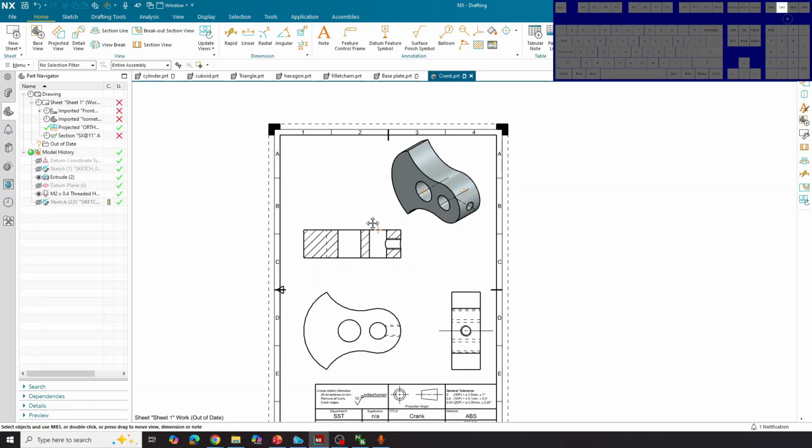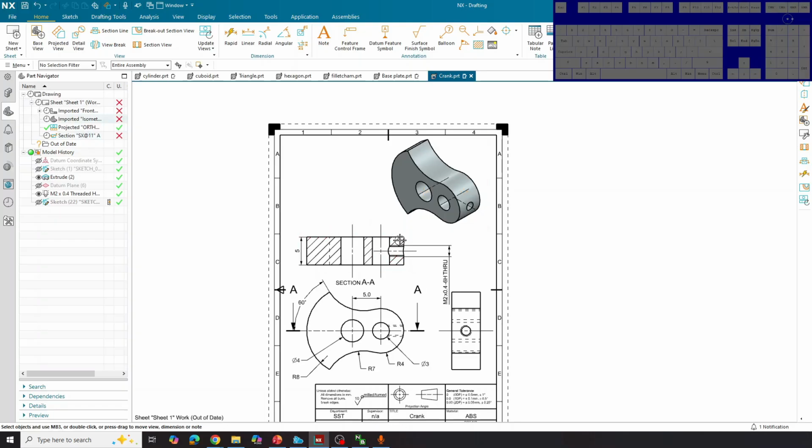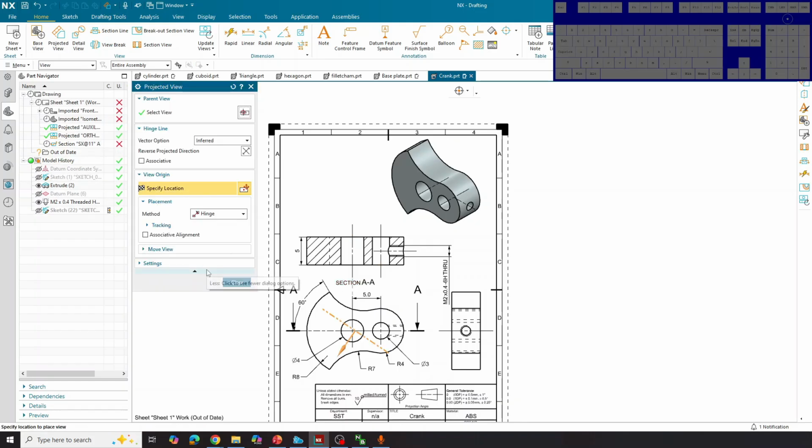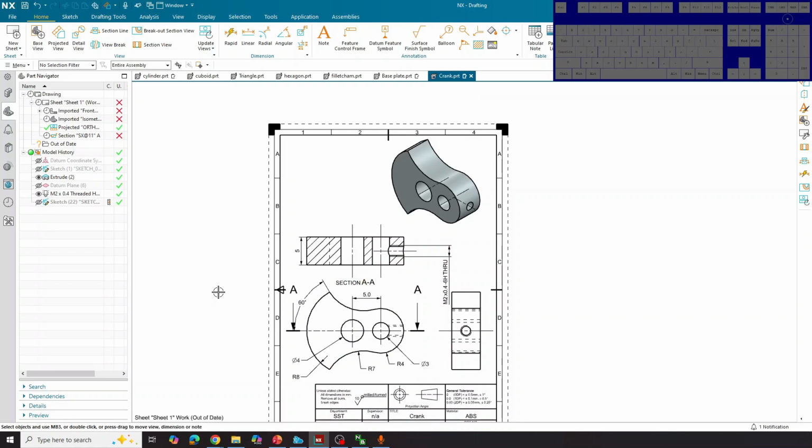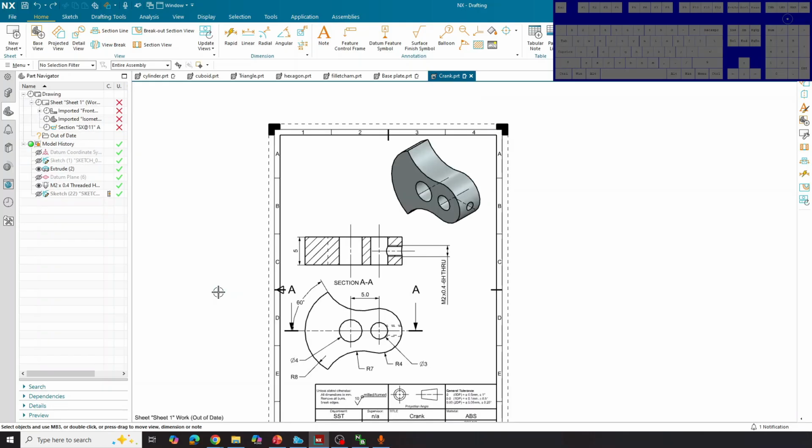And so, this sketch over here, it's the top view of this sketch. So, this is my front view. If I were to look from above, this is from the top view. Okay? This is technically a section view, but it's still a top view. Now, you only need as many views as is needed just to communicate the design, okay? So I felt like 2 was enough. So that's why I only have 2 views over here, okay? But you can have 3 views if you want to.